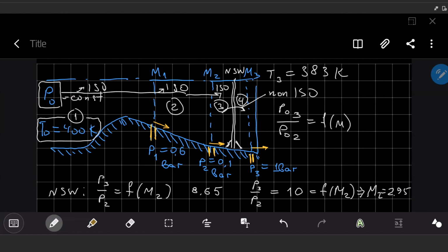This is why inside the rocket motor we measure very few points of temperature. Usually we measure only the pressure distribution, and we know all Mach numbers, we even know the position of the shock wave. And it gives a lot of opportunities for us, I mean, for the application of gas dynamics theories to the real case, real flow.